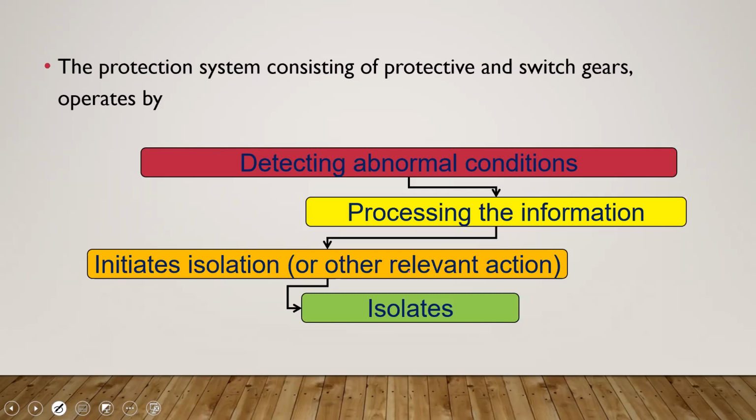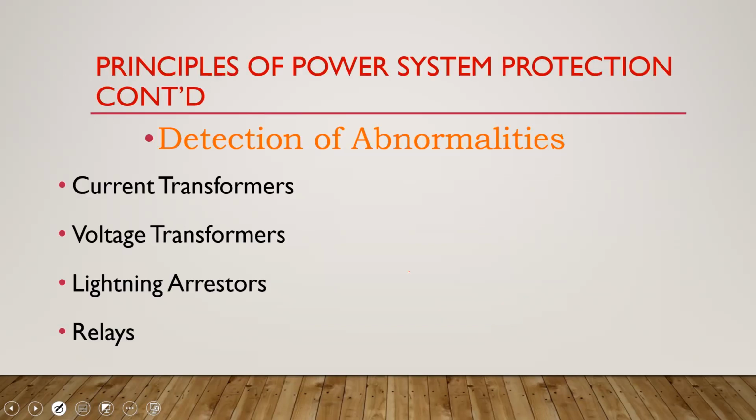But he didn't maintain the breaker, and the breaker simply didn't operate. And it escalated and came back into the unit. And before we knew it, the entire island was out. All right. So you are going to have escalation if the local or prescribed protection system doesn't operate. Good question anyway.